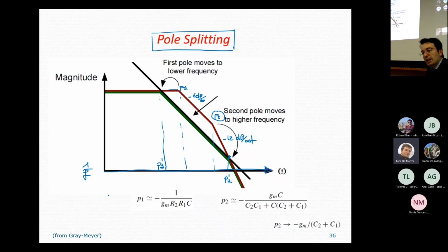So, for example, the headroom for the output value with respect to VDD is equal to the overdrive of transistor 6. Or the headroom with respect to the common mode input maximum value is the overdrive of transistor 3 plus VTP minus V threshold.